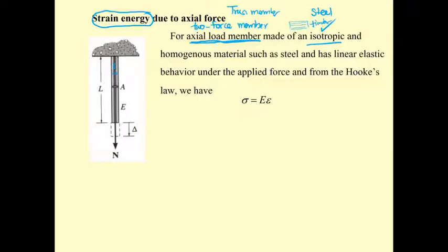Timber has the grain, so timber isn't an isotropic material, because it has properties perpendicular to the grain different from those parallel to the grain. The properties of the wood in these two directions are different. So wood is not an isotropic material, but with steel you can still test it any way you like.